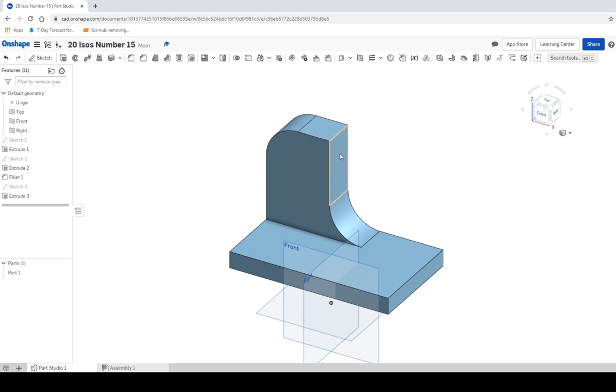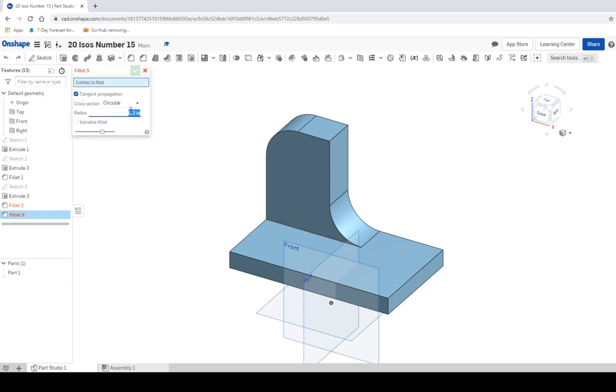Now that we've got that out of the way, we can use the fillet command again. I guess I could have done both of them at the same time. Hindsight is better. Anyway, fillet of 2, and hit the green check mark, and we can cut this away. And then the only thing that we have to worry about, looks like I did not do it. Here we go. I'll try it again. 2, click the edge. There we go. And then click the green check mark.